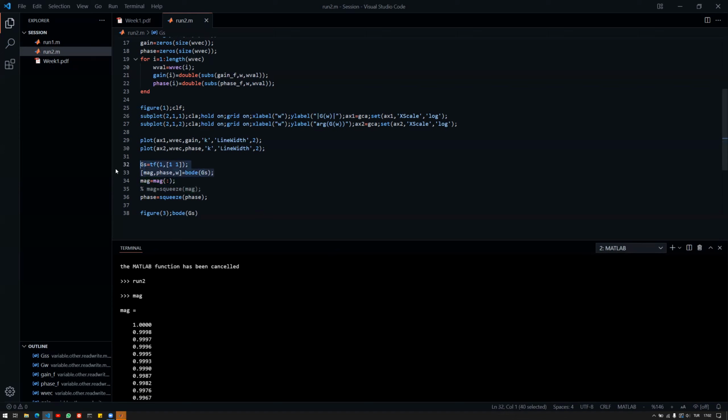As you can see in this case, if I type in mag, there are 2 dimensions used for input-output channels, and then there's a third dimension which has the actual element and the vector value in it. In order to get rid of it, I can use this approach, which gets rid of this structure, because there's no real need for it in single input, single output systems. Or you might also use squeeze, so it will get rid of the extra space. So it squeezes it down to a 1D vector.